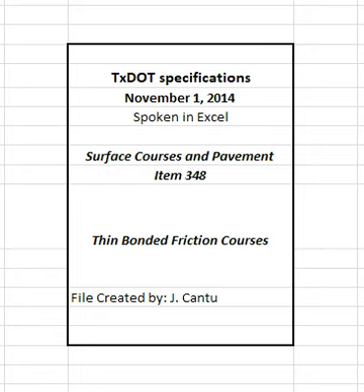Prepare the surface by removing raised pavement markers and objectionable materials such as moisture, dirt, sand, leaves, and other loose impediments from the surface before placing mixture. Remove vegetation from pavement edges. Place the mixture to meet the typical section requirements and produce a smooth, finished surface with a uniform appearance and texture. Offset longitudinal joints of successive courses of hot mix by at least 6 inches. Place mixture so that longitudinal joints on the surface course coincide with lane lines, or as directed. Ensure that all finished surfaces will drain properly.